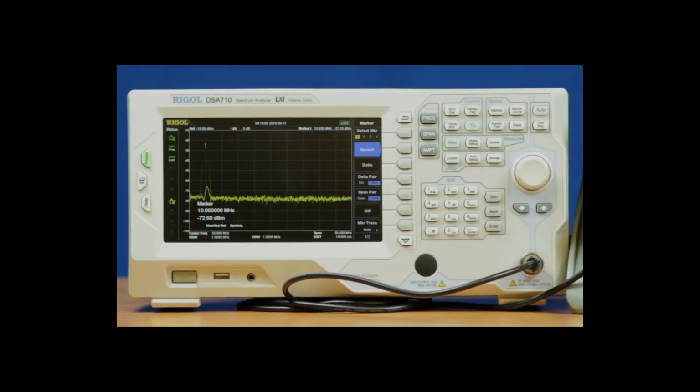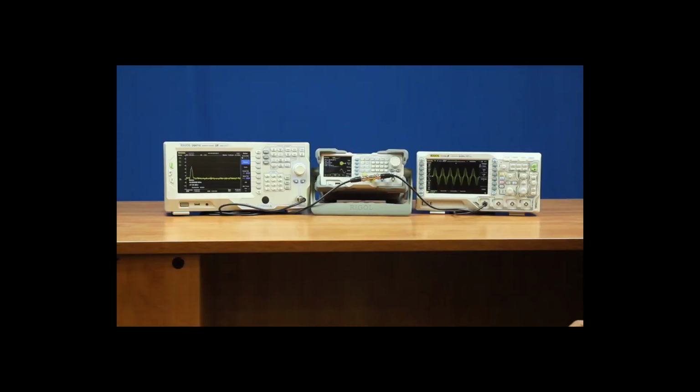On the spectrum analyzer, we can see that same modulation occurring, and what happens is every time the analyzer sweeps, it captures a different power level at that frequency. And you can see it moving up and down as it's getting more or less power. Here you can also see it dramatically changing from a relatively high minus 25 dBm all the way down to the noise floor. So this is an amplitude modulated signal where the power or the voltage, the amplitude, is being modulated over time.